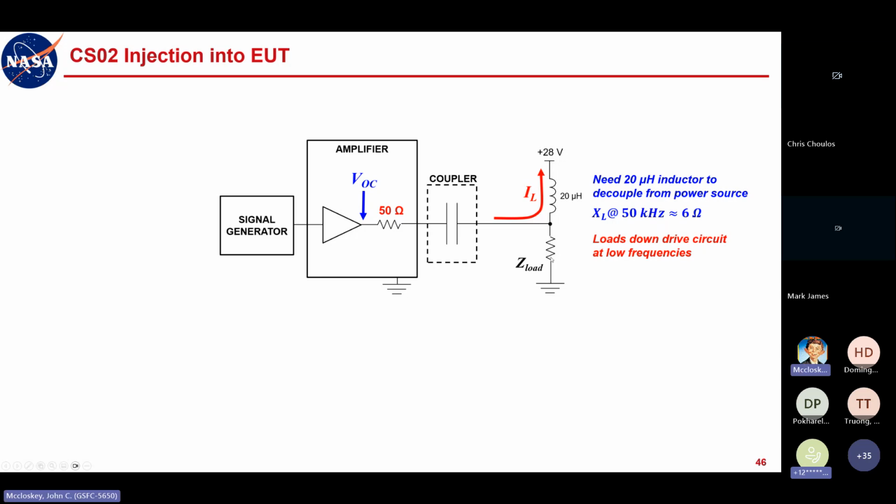At low frequencies, where the input impedance of your device under test may be fairly high, this is going to be a dominant path. A lot of load current's going to flow in here, and it's going to affect the injected potential. So you needed that higher drive level to compensate for that at the low frequencies. But then it's just kept at that same level, the 1 watt across the whole frequency range.